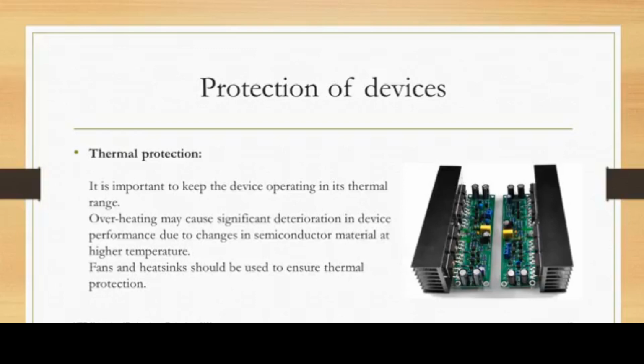The heat must flow from the device to the case and then to the heat sink in the cooling medium. A wide variety of aluminum heat sinks are commercially available, and they use cooling fins to increase the heat transfer capability.